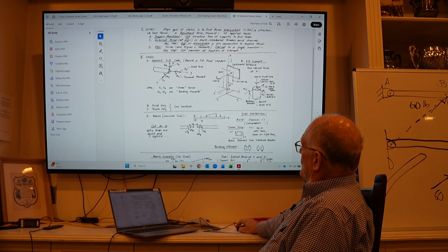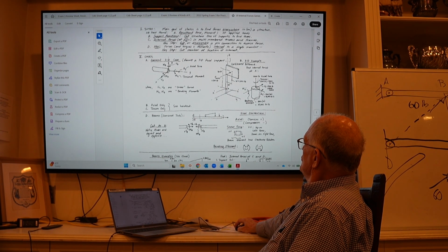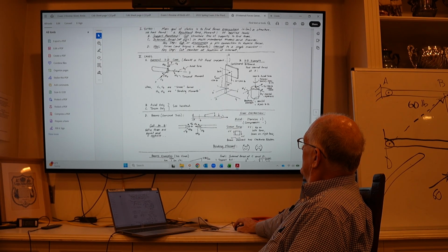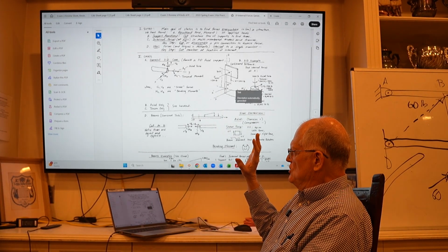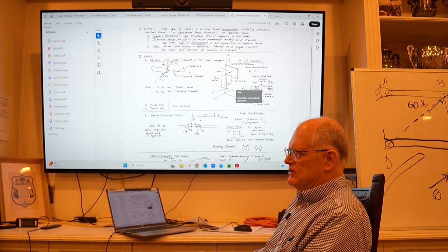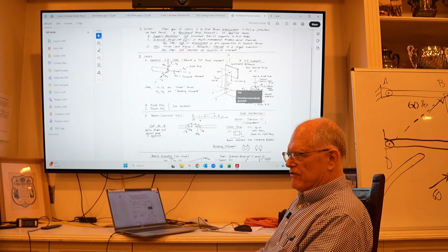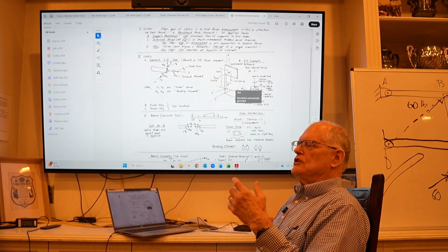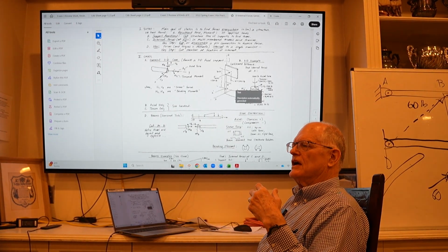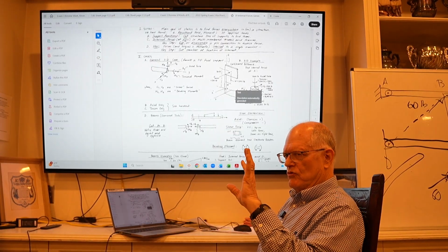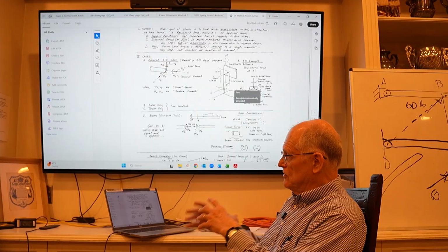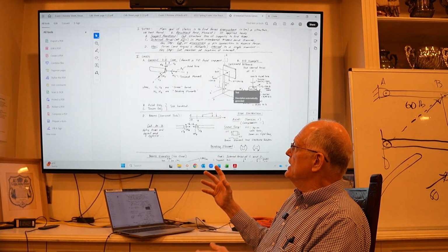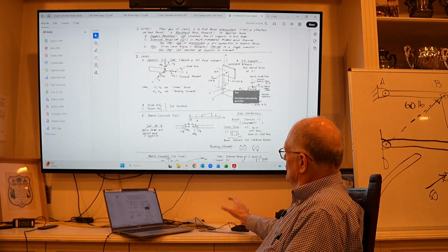And so in the general 3D case, you can actually have two directions of shear. You can have an axial, and then you have two directions of bending moments about two different axes, and then you can have a torsion about the shaft. So ultimately, in the full-blown 3D case, you can have three forces, two bending moments, and one torsion. When you get to mechanics of materials, you'll deal with what are called combined loading cases, where you have stresses due to all of these.